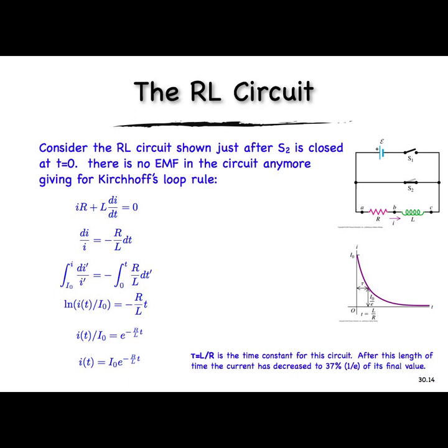But the moment I close the switch, as that current tries to flow, it produces an EMF in this coil that opposes that. And as a result, current does not flow initially. Hence, at time 0, there's no current flow. And then as time continues, the current slowly starts to build up. So this restricts the change of current. So it doesn't change instantaneously. Instead, it takes some time to build up.